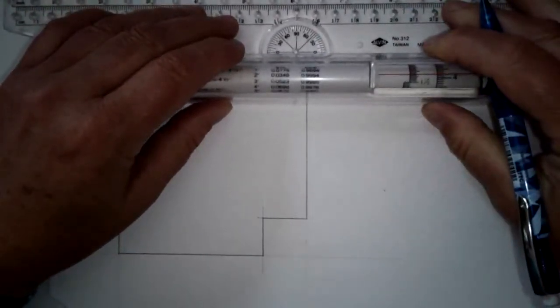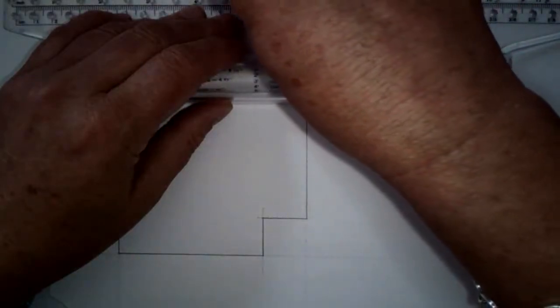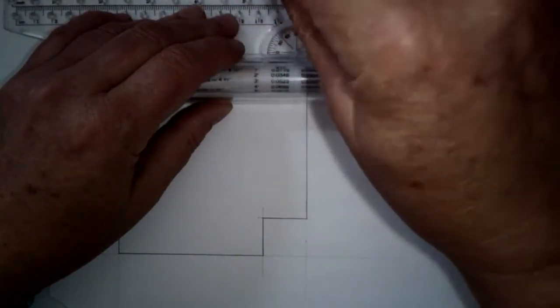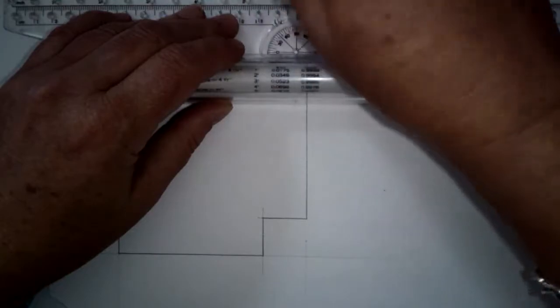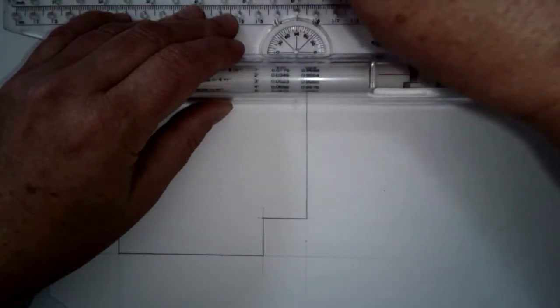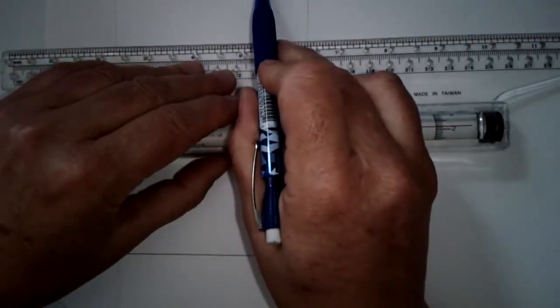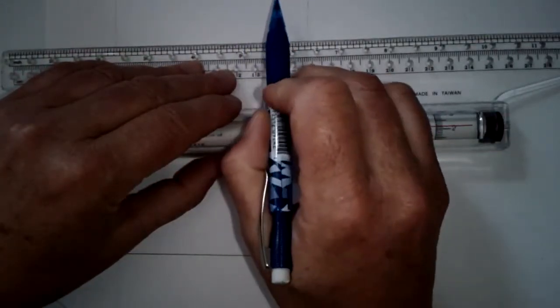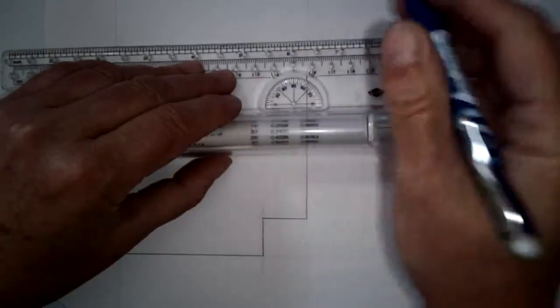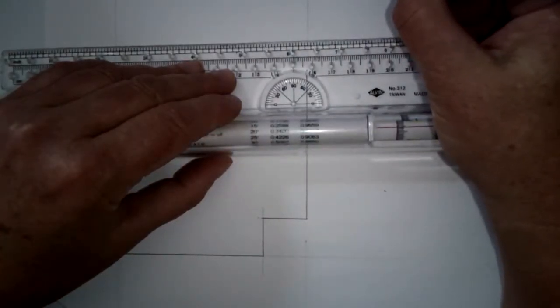And then here's a thin line, and you'll see that I'm going to use a different pencil holding technique. I'm going to roll the pencil and drag it against the straight edge to try to create a line that stays thinner but still is just as dark as that line. And you can see there's a difference in line weight there when I'm done, and that's a thin line.